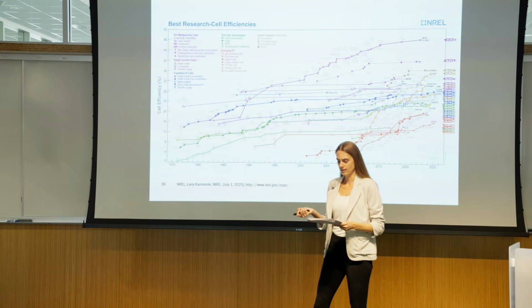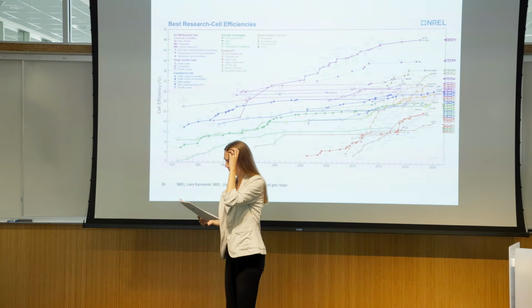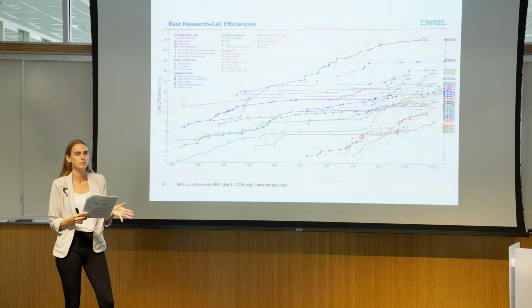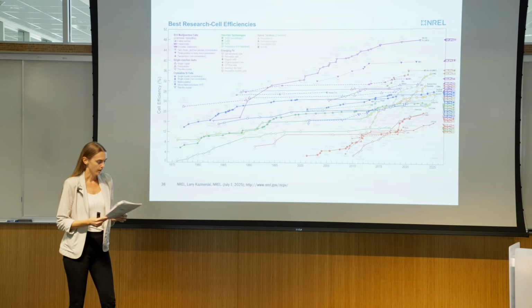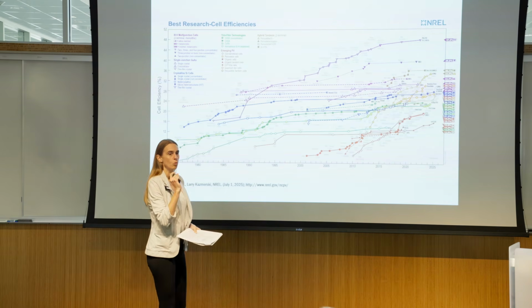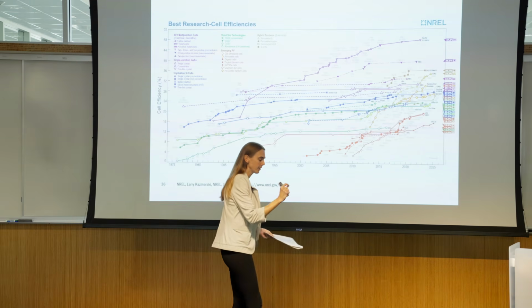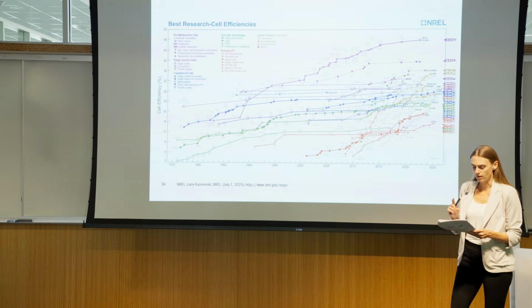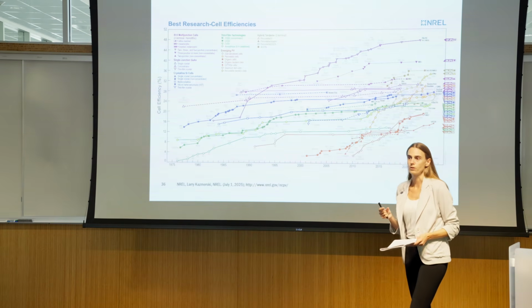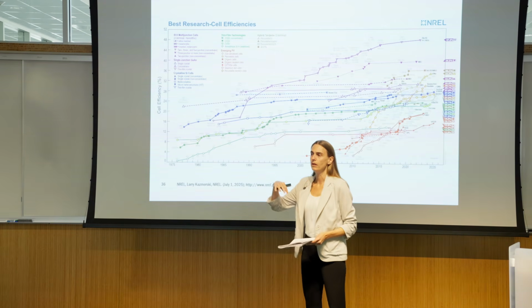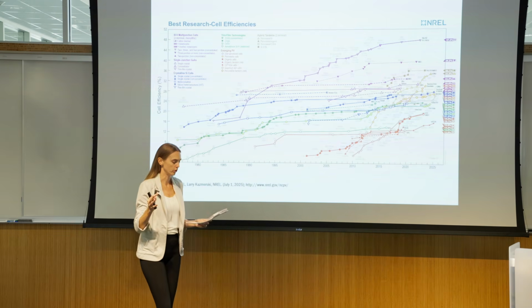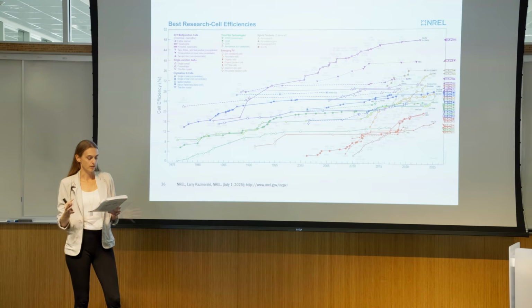To understand multi-junction cells, it's important to understand that different semiconductor materials and PN junctions have different band gaps, which is the minimum amount of energy required to knock an electron free of its bound state. The different wavelengths of sunlight have photons with different amounts of energy. So multi-junction cells allow the PV panels to take advantage of a much broader spectrum of sunlight.